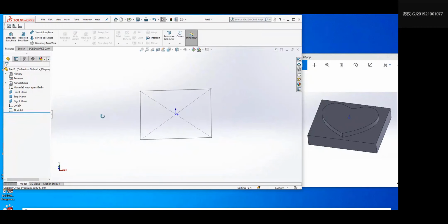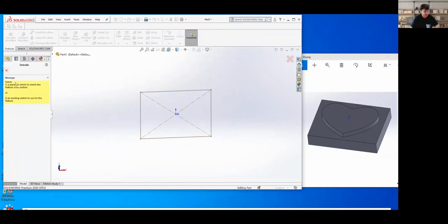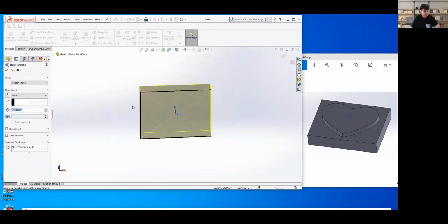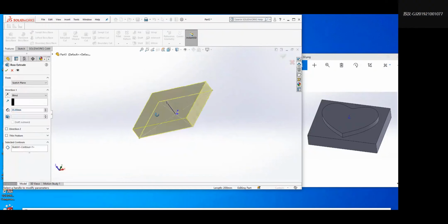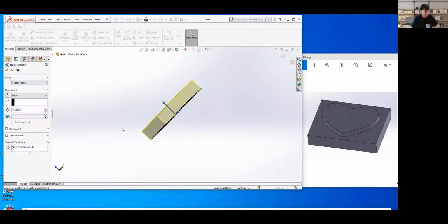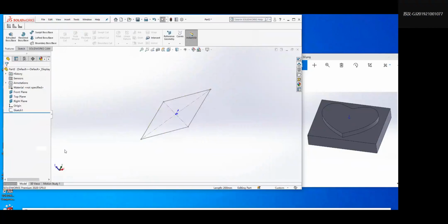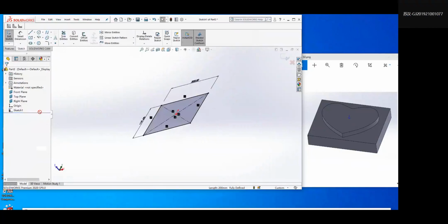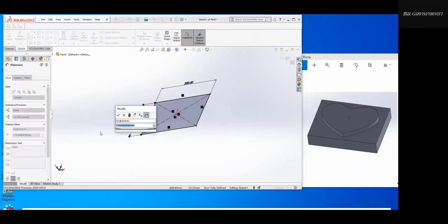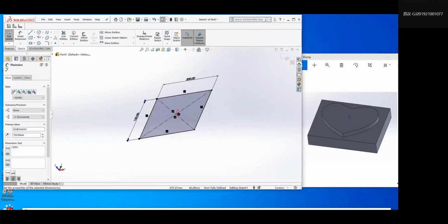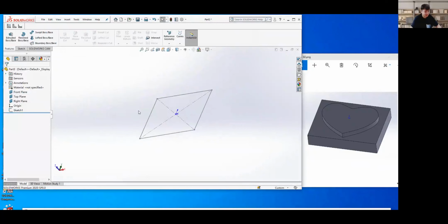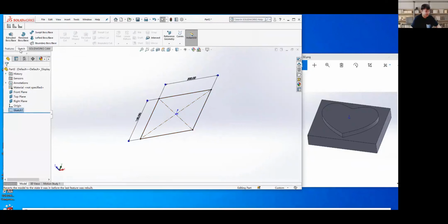If you don't select the sketch and you give it extrude, you will see a message to select a sketch or something. Here you can just select it, it's fine. Yeah, but I saw all the professionals just exit from the sketch and then go back for extrude. It's fine. It's the same, it doesn't matter, okay?